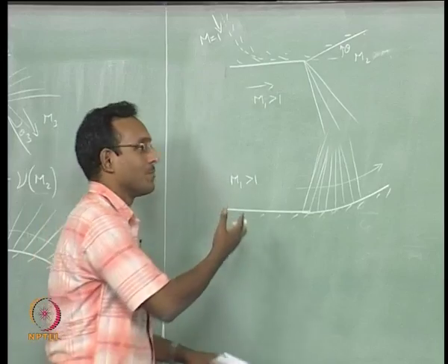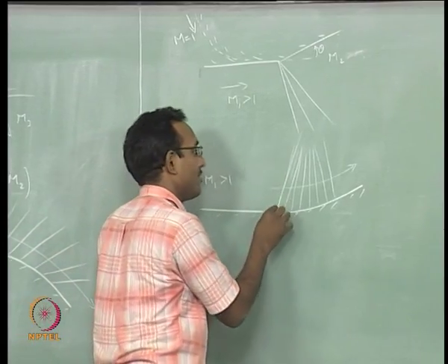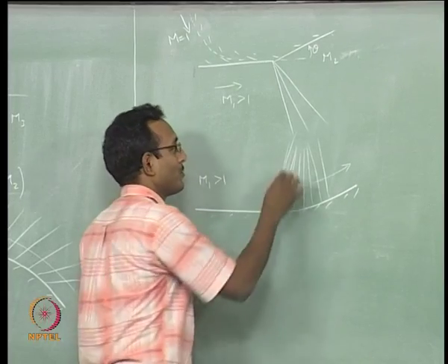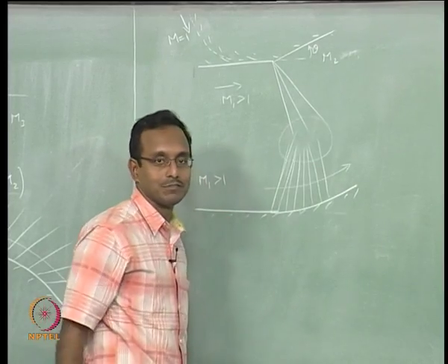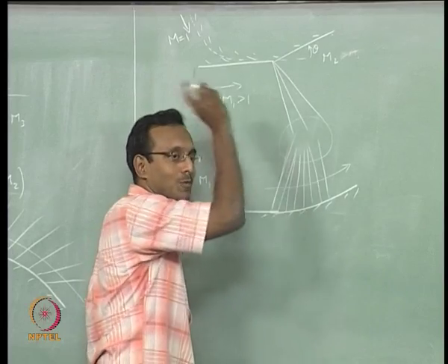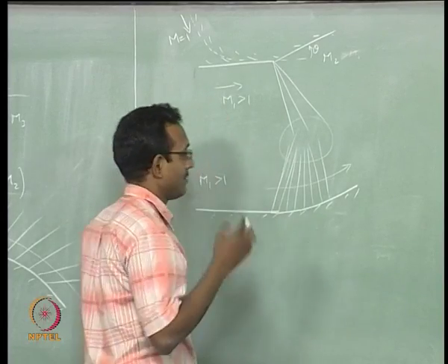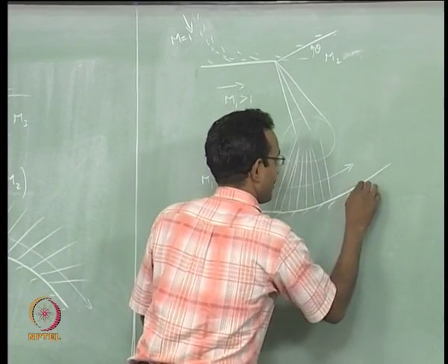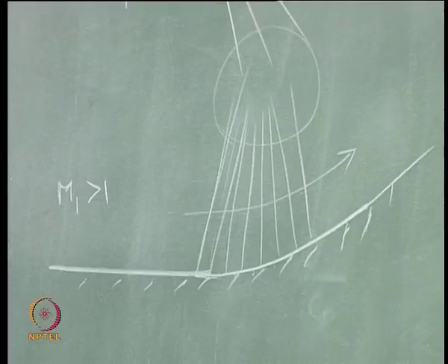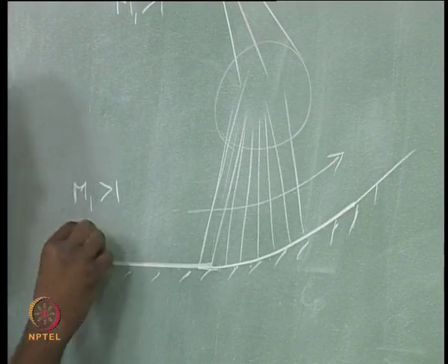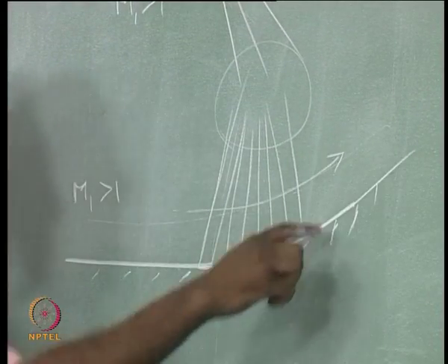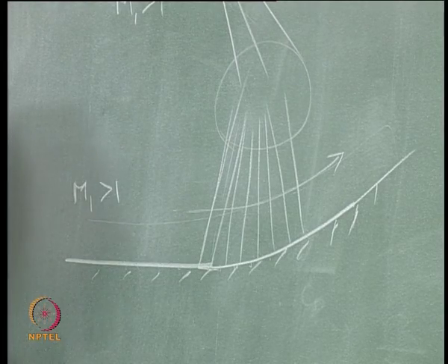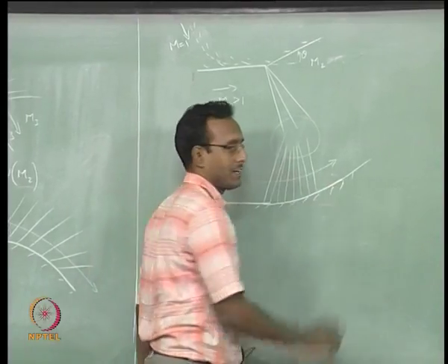is your compression phenomenon. It is going to have a whole bunch of compression waves coming together, and of course we won't worry about what will happen when they come close to each other. They eventually collapse to form a shock, oblique shock finally. We won't worry about that part right now, we will deal with that after some days. And it is going to go through this. This particular problem, very close to the wall of this particular smooth compression, I can still use Prandtl-Meyer angle to solve this problem. I will get the Mach number here exactly that.